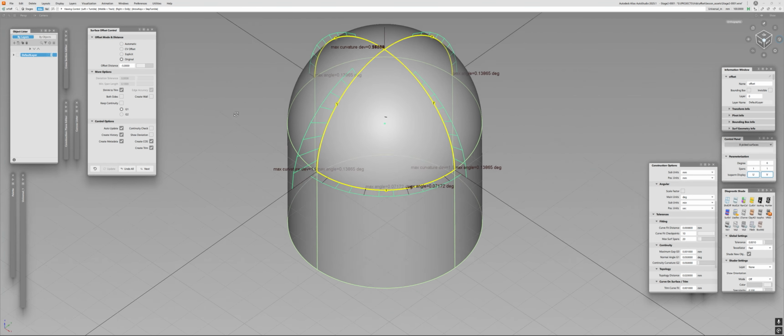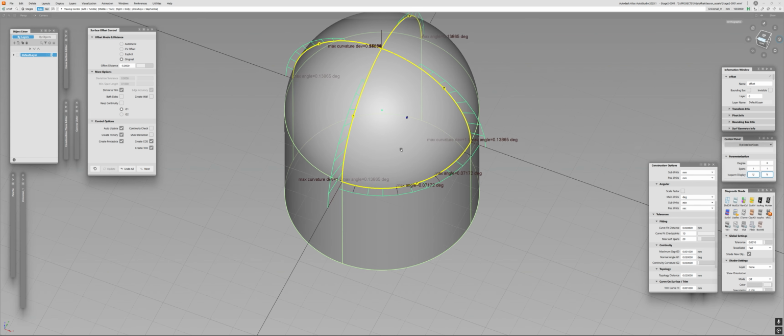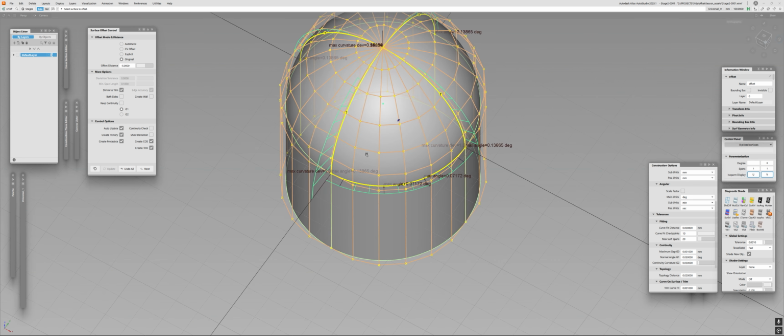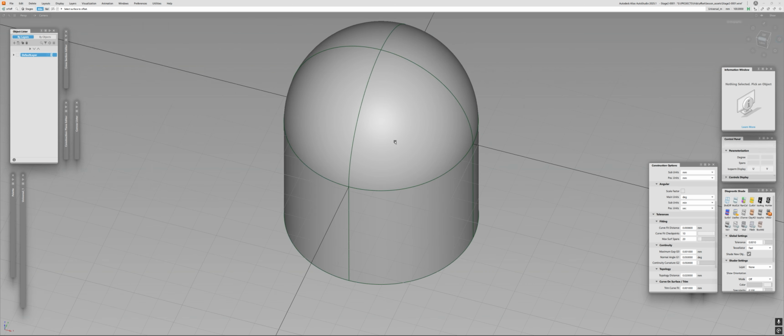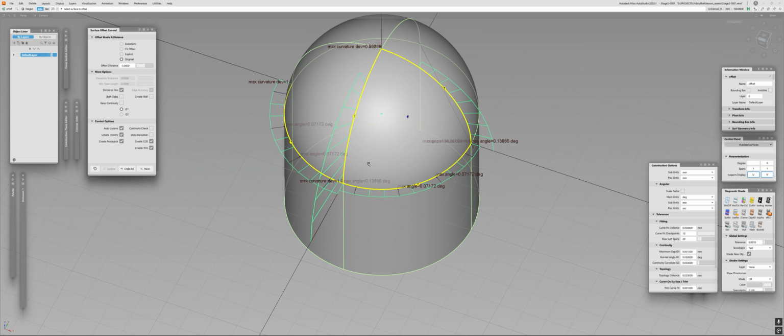Well, what we have here in the original is that we actually eliminated the problem of position. Why was that? Well, that's because we reconstructed these surfaces with the same amount of control vertices as the original surface. So in this regard, it may give you a better result and an easier continuity because the surface is simpler. So now if I check it, you're going to see that now I don't have an issue with position, finally. But of course, all the other issues are still there. So I have tangency issues all over the place, and they are big. And of course, I have a curvature.